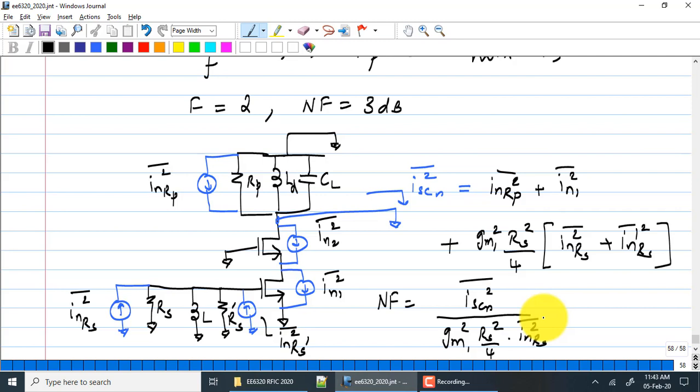No, not okay. So what is not okay? Okay. So 4 noise sources, 5 noise sources. Let's assume that this noise is going to circulate inside this, so let's ignore it for a moment. Looking at the short circuit noise current, this noise current will directly go through the short circuit. So that's the first term I have written down. IN1 squared has 2 paths, to its own RS or to 1 over Gm of M2. So it will go through 1 over Gm of M2 and it will go to the short circuit. So IN1 squared will appear directly in the same.